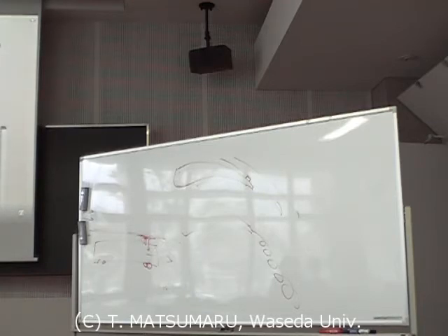And here's where it comes to what vortex generators actually do. Vortex generators allow you to control the point of separation better by delaying it further. This means that with more intense curves in your geometry, you can keep that flow attached for longer and thus get better efficiency for your given profile, or make the flow do what you want it to do. You understand?